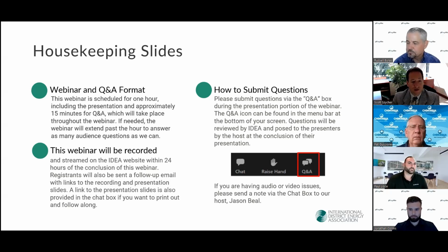Specifically, we'll discuss the need for flushing, including what velocities are necessary, the required testing and monitoring activities for these hot water systems, the best practice timelines to follow, and what types of disruptions might necessitate a remedial flushing, cleaning, passivation, and disinfection regimen, and what to do if you have to lay up your system or otherwise delay bringing your system online for an extended period after the flushing and cleaning and passivation process.